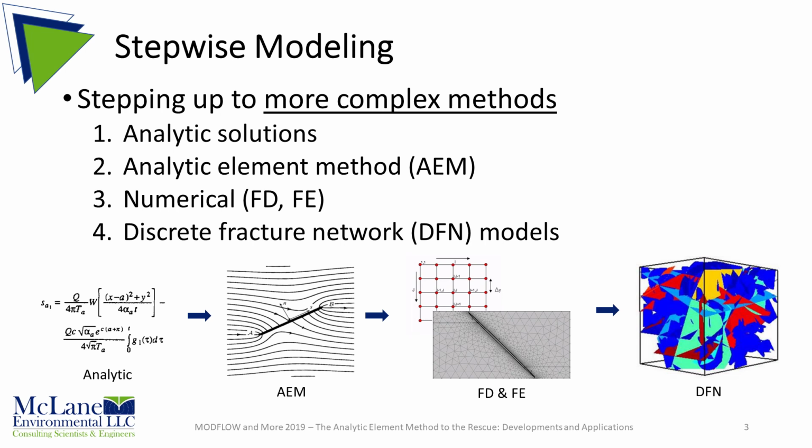Stepwise groundwater modeling basically involves starting with a simpler approach or method to scope out the problem, and then applying more refinement or sophistication until you reach a solution that embodies an acceptable level of complexity and confidence.